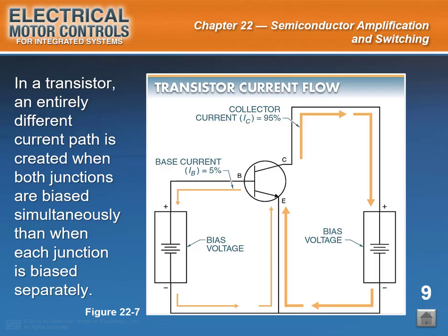The load resistor limits the current flow to a safe level to protect the transistor from damage, while superimposing an Ohm's law voltage across the load that is proportional to the current flow through it. That voltage can be used as the output from the amplifier or switching circuit.